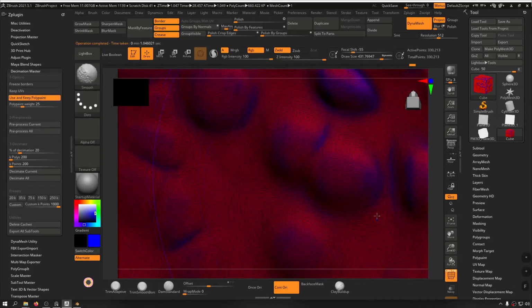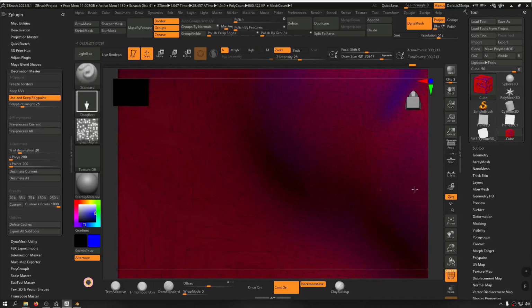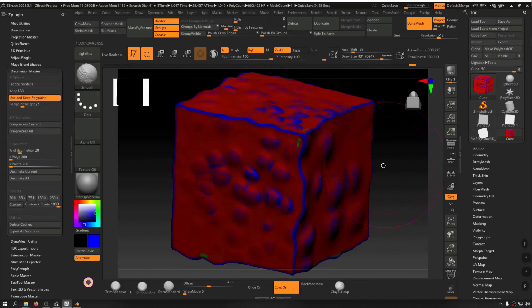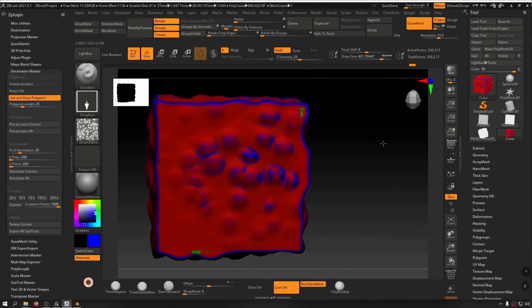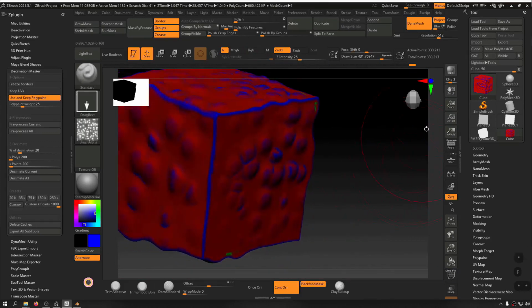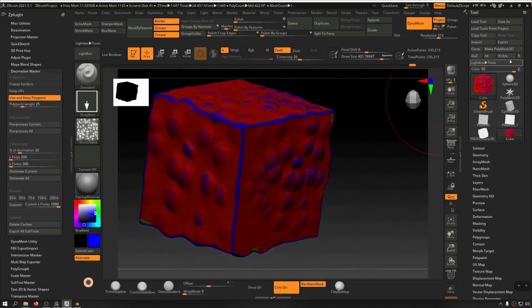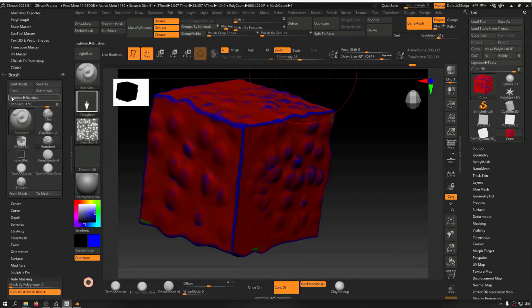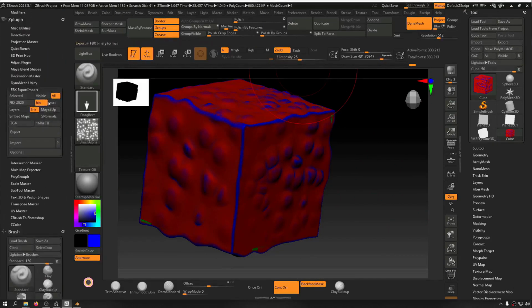data for us. You see, although the poly count has been reduced dramatically, the result is going to stay the same. And when you are going to export this to Unreal, you either can export it using these exports, or you can come down in here and there's a plugin called FBX export that has a lot of options.